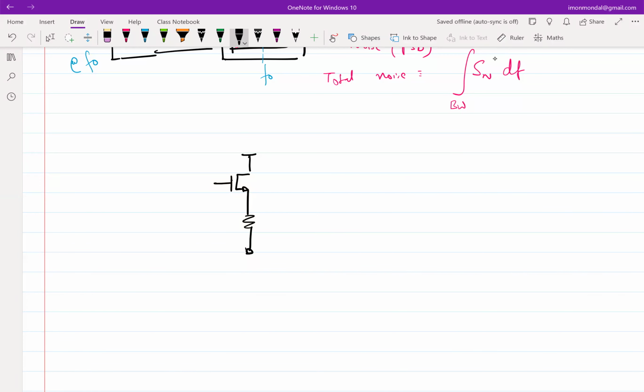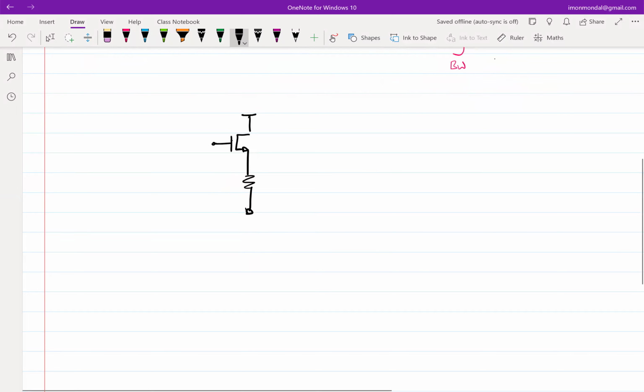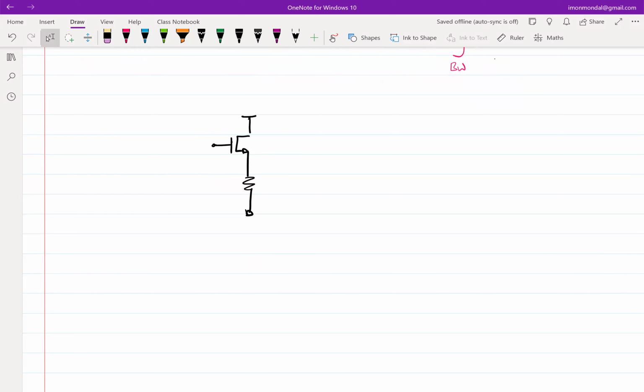So I'm going back to the two-port input referred noise model, because in the last class I said I'll show you with an example. So let's close this, and I'll come back to dealing with noise at a system level after that. Let's say I take a trivial example of a common gate amplifier where this is incrementally shorted, and this is my two-port.